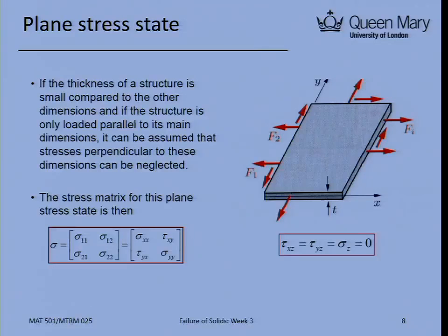That is called plane stress, which means the stress component in the through thickness direction, sigma 3 or sigma z, is equal to 0. Anything relevant to z will equal 0.